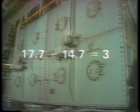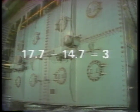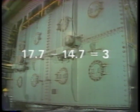If you've ever looked at the water boxes on a condenser, you may have wondered why they're so heavily constructed. Well, this seems uncalled for when you consider that typically the pressure in the water box is no more than 17.7 psi. Since atmospheric pressure is about 14.7 psi, by subtracting 14.7 from 17.7, we can see that there is only a 3 psi difference between the pressure inside the water box and the pressure outside the water box.